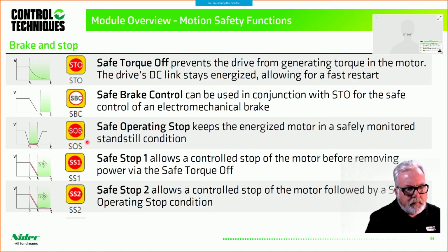Another one is safe operating stop, or SOS. Keeps the energized motor in a safely monitored standstill condition. Now, again, is there a set way that these should be used? Is there any sort of rhyme or reason? No, there is not. You are free to utilize these functions in the way that you have seen fit to come up with your safety setup.